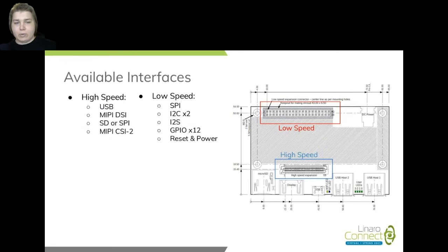We have also a high-speed connector. That is a connector with a very fine pitch, which is again not very friendly for beginners, but it features more advanced interfaces like USB, MIPI DSI, SD, or SPI, MIPI CSI too. Next slide, please.